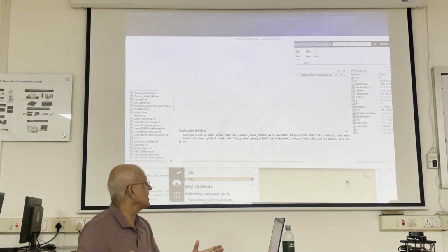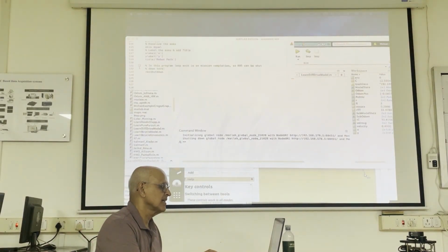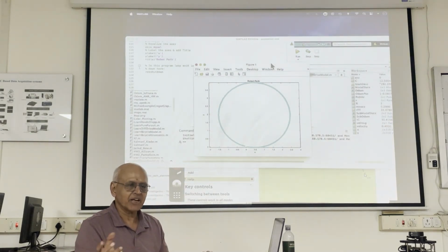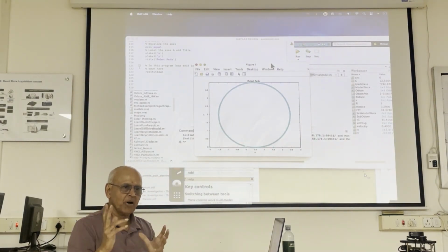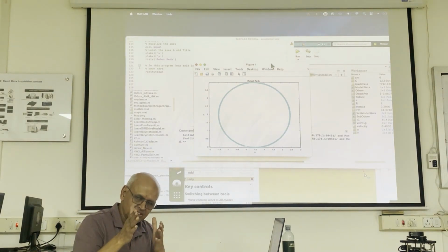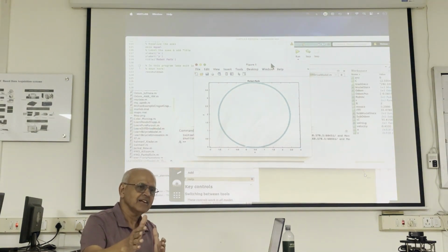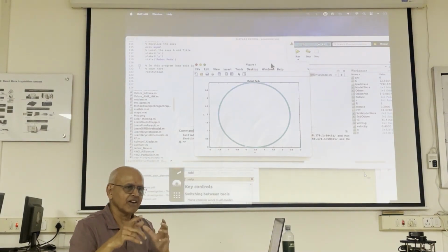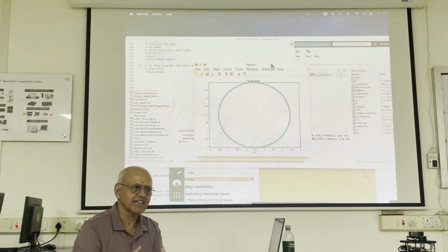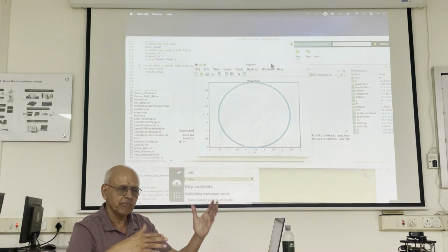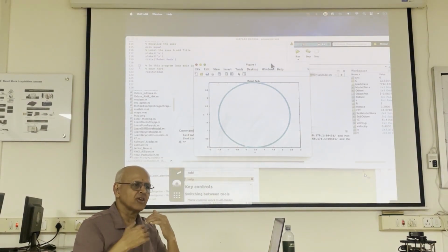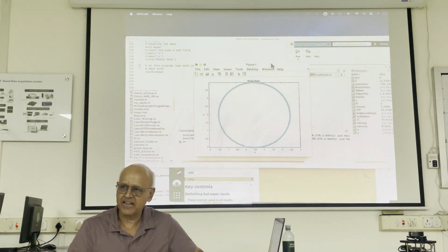And then you have to do it with the correct alignment, because the alignment is very important. The robot's angle with which the LiDAR is looking at the cylinder is changing. So you have to be conscious of all that. Not you, but the program has to handle it through transformations. Otherwise the map will be all over the place. So this is something that you have to be very aware of in mapping.